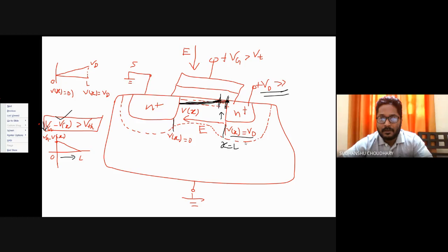Okay. And also because of the same effect, that is you are increasing Vd, now the channel is tapered, that is of wedge shape, that is some electrons are now missing here in the channel. Earlier it was straight, but now it is of wedge shape. So that means some channel charge is lost here. So to accommodate that lost channel charge, your depletion region under the gate should also vary in a similar fashion, to fulfill the space charge neutrality principle.